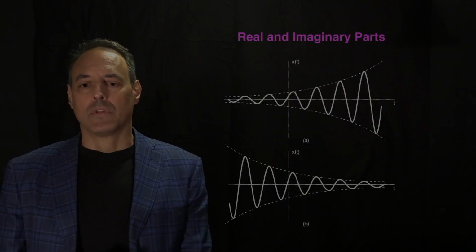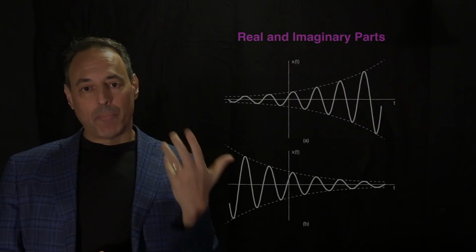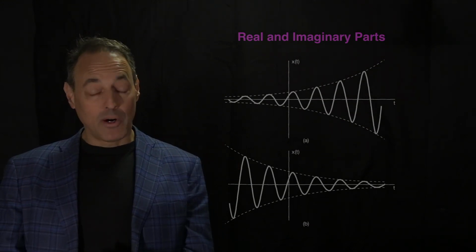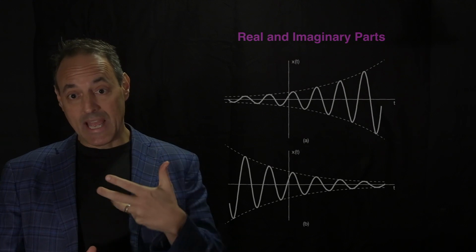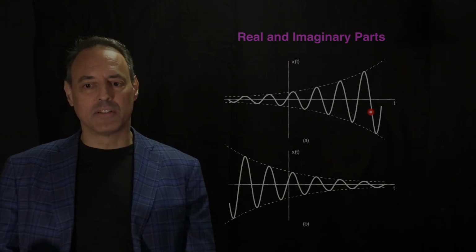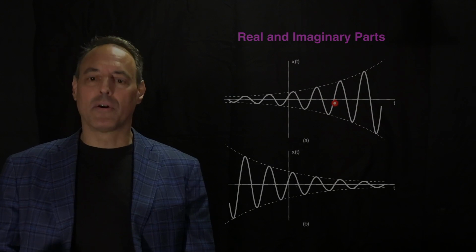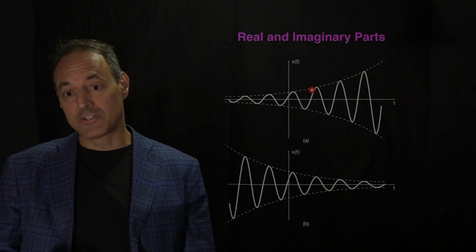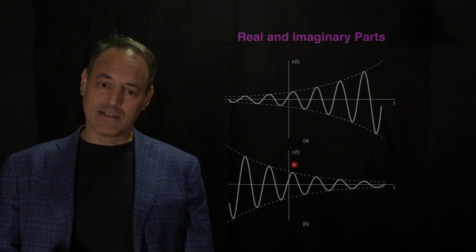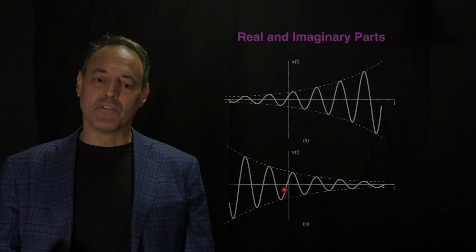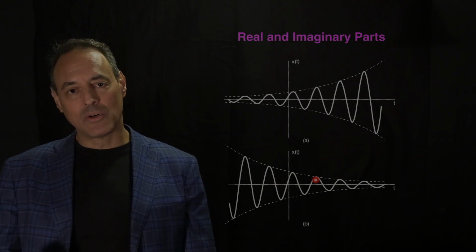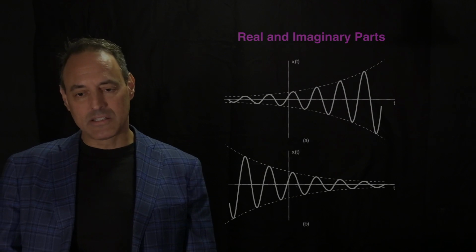All right. What happens if we have real parts of a signal plus these imaginary components? So the real parts usually are exponentially growing or decaying, and the imaginary parts are oscillating. So more generically, here's how you would represent signals. This is if you have a real part that's positive, so the signal does exponentially grow, but it's oscillating at the same time. And same thing here if you have a negative real part, the signal is decaying to 0 and oscillating.